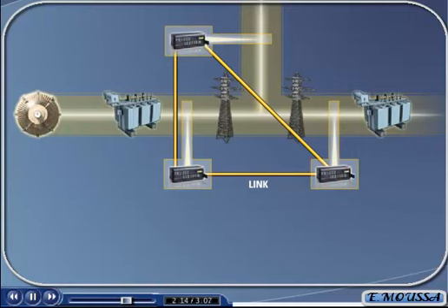If there is a failure of one communication channel path, the relays will automatically switch to a backup master-slave mode. The relay that is still in communication to the other two relays will be the master, and the other two will switch to slave mode. The master relay will perform the differential element calculations for its location and both of the slave locations. If a fault occurs, the master will either trip its own breaker and/or send the appropriate signal to one or both of the slave relays to clear the fault.